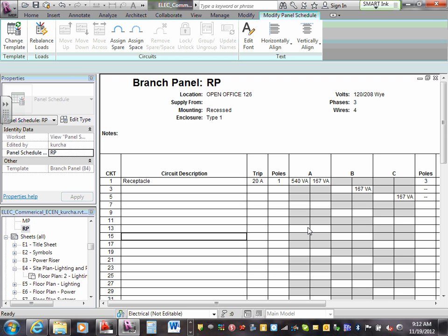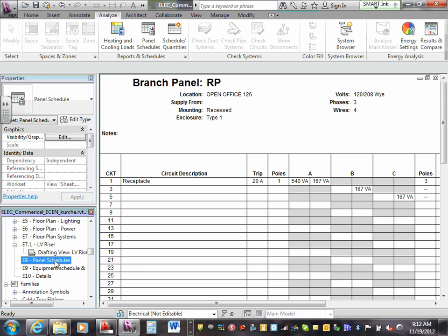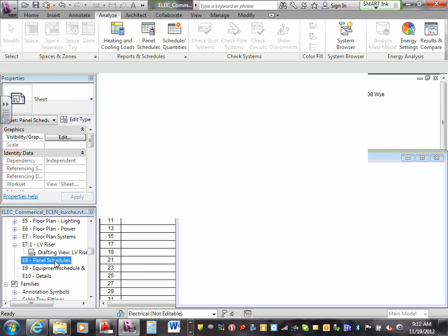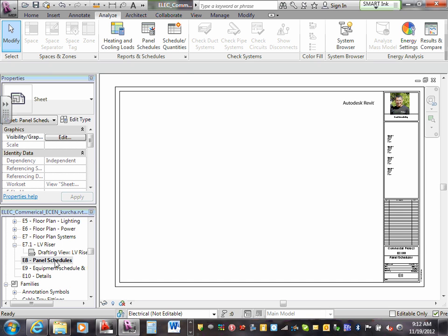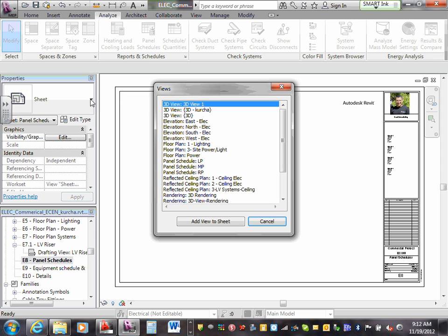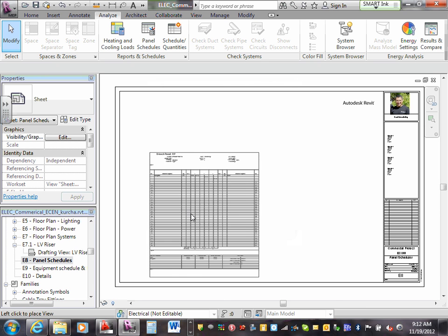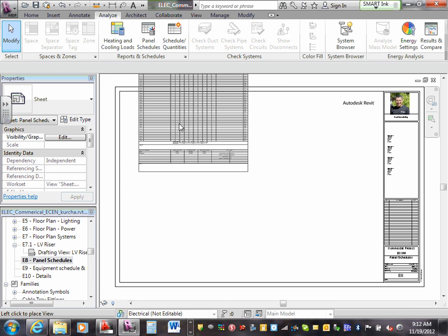So when you're done, here's what I would like you guys to do. Go to E. Which E are we going to drop them in? We're going to drop in E8. Can you guys see? Everybody click on E8, please. Right click, add view. Can you guys see the templates that we have? I want to add, let's just say, the receptacle panel. Add it. Okay, here's my receptacle panel.